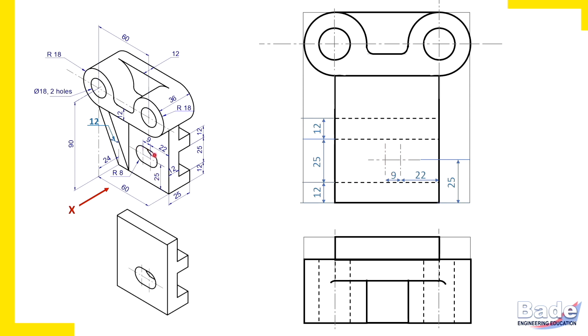to draw those curved edges, and the radius of each curved edge is 8 millimeters. So draw those semicircular edges here with radius 8 millimeters. And then complete the shape by small straight edges here, parallel to length edges. So this whole opening in the front view is complete.